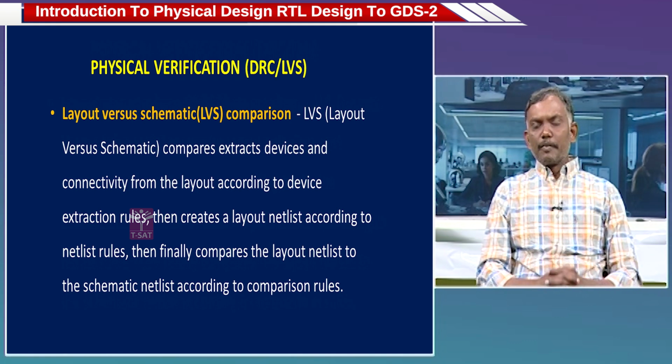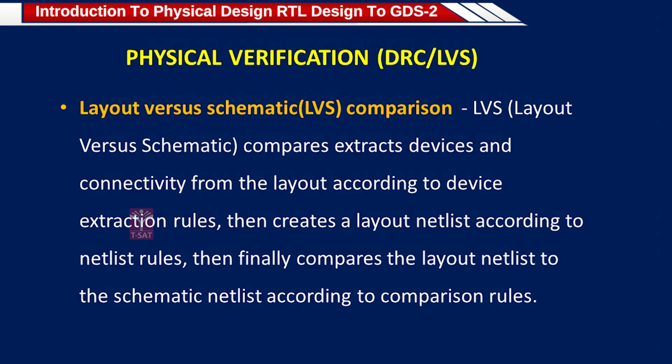So for the complete chip, at the device level, we need to verify DRC as well as LVS. Our GDS2 is the layout. And we are dumping one more netlist with the PG pins as part of our outputs. That post PNR gate level netlist with PG is called the schematic.